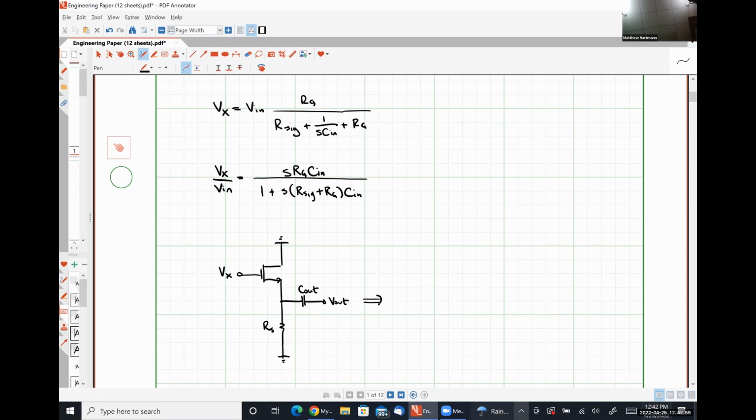So I've just truncated everything to the right of the red dashed line as something that I feel will be pretty easy to analyze. So how I'm going to approach this is I'm just going to use the small signal model. I know that this is extraordinarily similar to what we saw in ELEN 335. The only real difference here is the presence of that capacitance C out, which might have some role to play. So just to be on the safe side, we're going to go to our small signal model and rederive things here really quick.